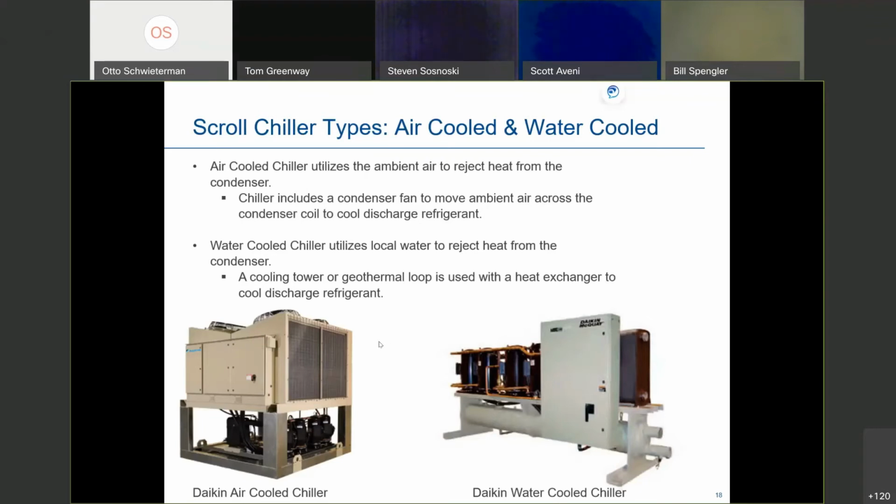But if you're in a part of the country where water is expensive, these water-cooled chillers could actually be mitigated or neglected due to the water costs that you're going to have to provide to that cooling tower to overcome that evaporation loss, which is one of the benefits of the air-cooled chiller, and why air-cooled chillers are generally going to be cheaper than your water-cooled chiller application will be. So that's one main reason why most people decide to use an air-cooled chiller instead of a water-cooled chiller.